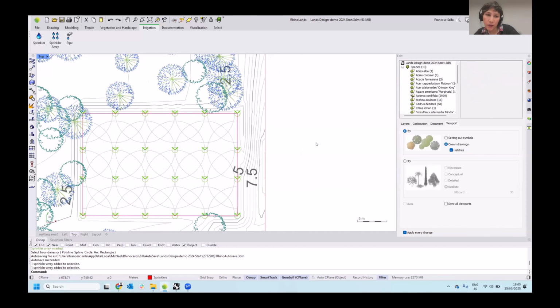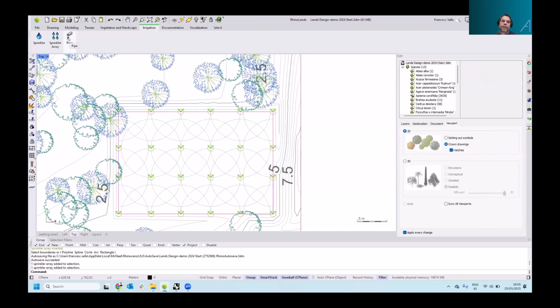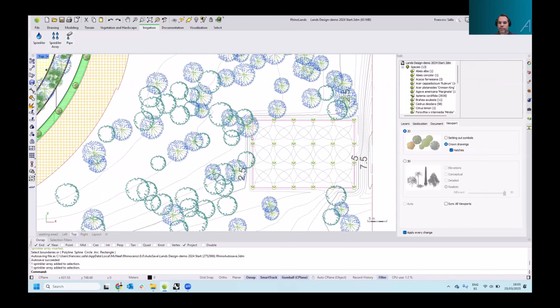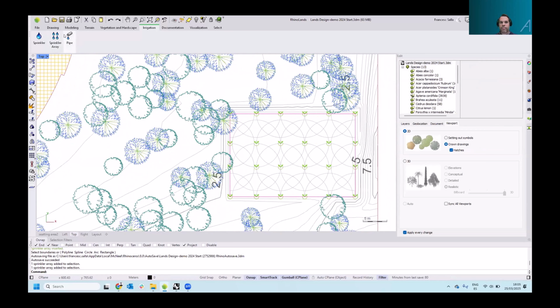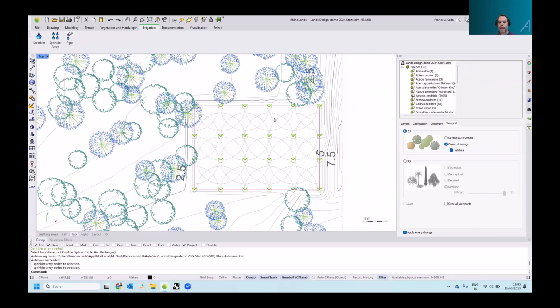And the piping can link them automatically. Yeah, the piping commands are basically 2D lines that can link different sprinklers. They are 2D lines with data according to the pressure and diameter, but they just have a 2D representation. It's a simple command, but you can quantify them according to the total length of piping systems, and it's also an interesting tool to link sprinklers automatically.